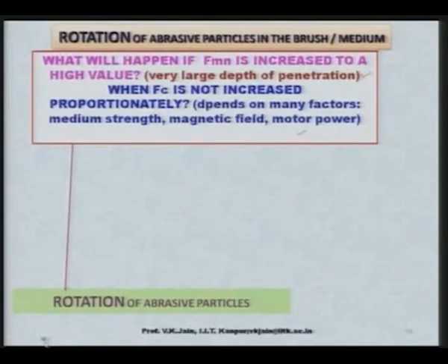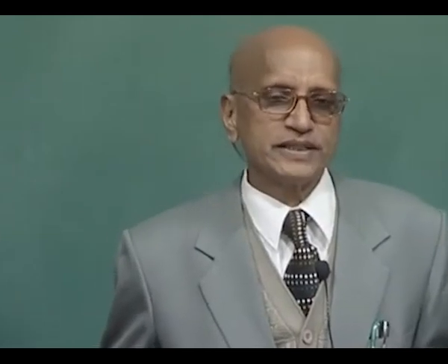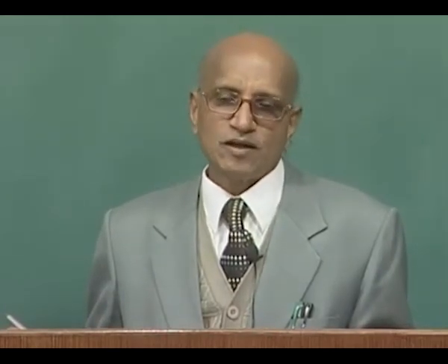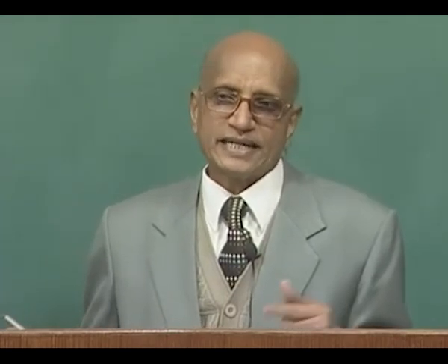Now, if the cutting force does not increase proportionately, then what will happen to the abrasive particle? Two possibilities are there: either the abrasive particle remains implanted in the workpiece, or it changes its depth of penetration such that the cutting force becomes larger than the resistance being offered by the workpiece material, and this is exactly what happens during MAF. We have tried to show it through experimental observations on the finished component, as well as computation or application of the finite element method.